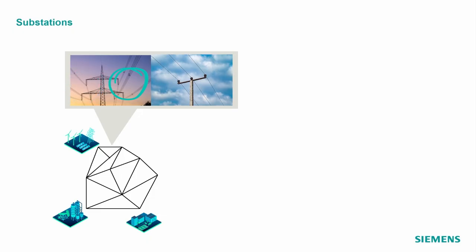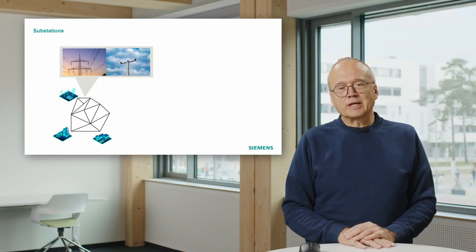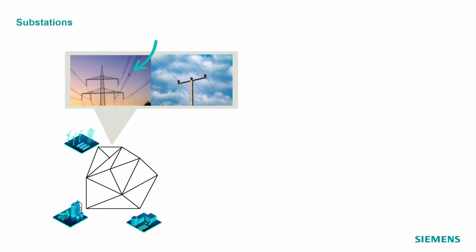What you also see is a so-called earth wire on top of the tower. This earth wire does not transport any energy normally. The reason for the earth wire is it is a lightning protection for the line, and it often also carries optical fibers for communication nowadays. What you also see in this picture is that every one of these 3 conductors of the system consists of 4 individual wires. That is state of the art for extra high voltage.